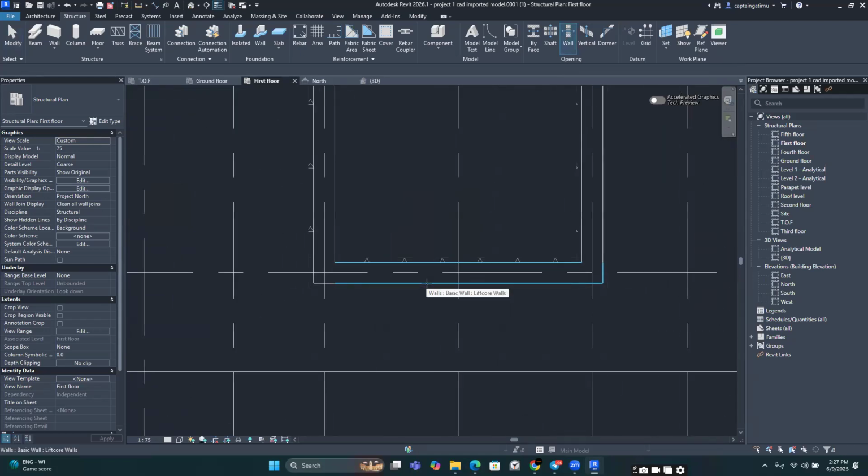If you look at this point, this wall has been highlighted, meaning this opening will be formed in this wall. So I'm going to left click. And then after I select the wall, I want you to look at my cursor closely. You're going to notice that it has a rectangular polygon to its bottom right. And this allows you now to make the opening.